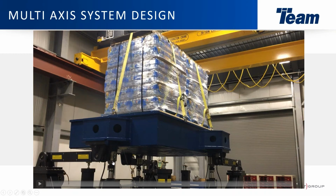So you can see if you operated 3 actuators in phase, you could get the vertical motion, and then operating them out of phase, you can get the pitch and roll motions as well. As I mentioned earlier, these 3 cross beams provide the constraint for your yaw motion, as well as the X and Y dimensions.